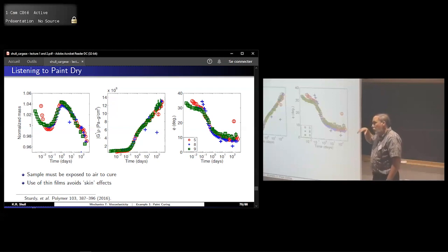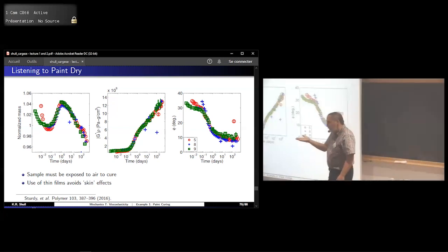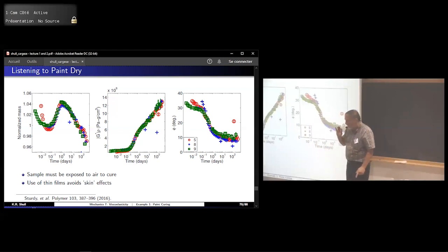If by adhesion you mean wetting, yeah, it needs to all be in contact. But the forces are so small that it's not really an issue. And also it's a thin film. As for stresses, we've never seen any of these things cracking because the stresses just get relieved by shrinking in this direction. So that's another advantage of dealing with a thin film. My take is the films are thick enough that they're representative of bulk properties, a few microns, but thin enough that equilibration and other mechanical effects we don't have to worry about.